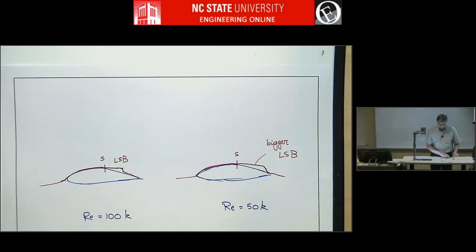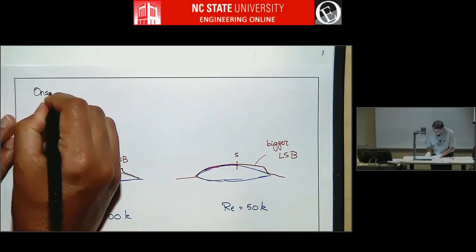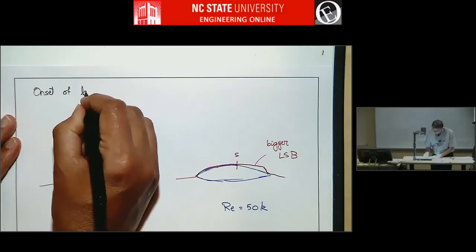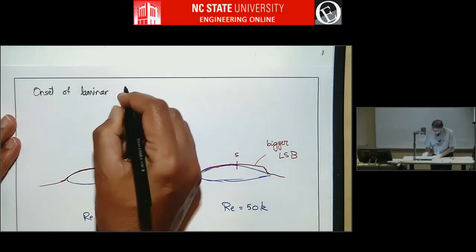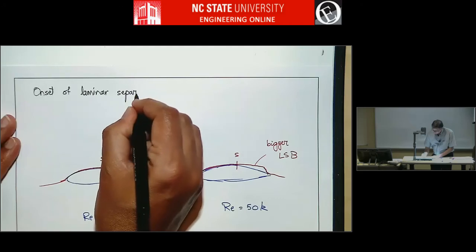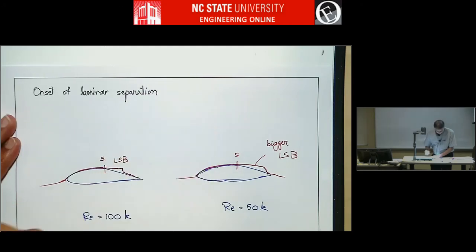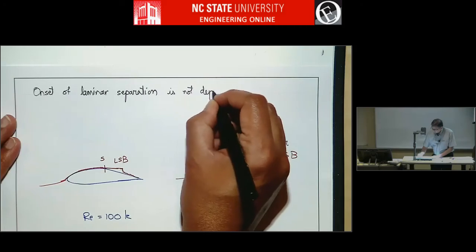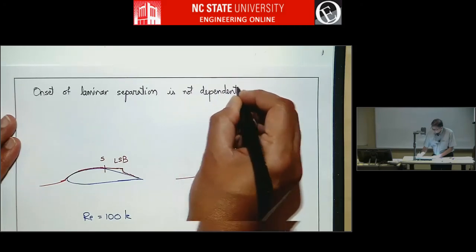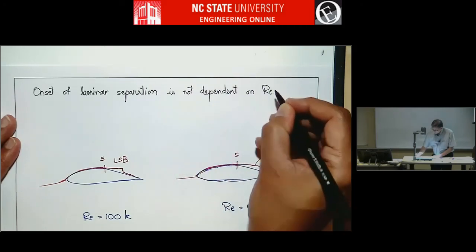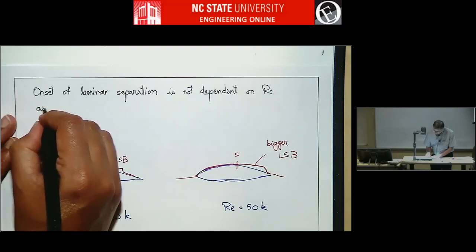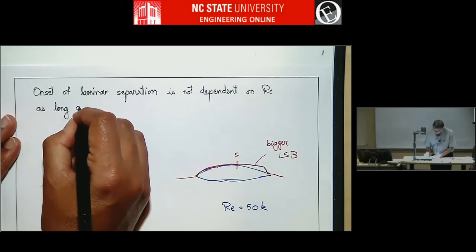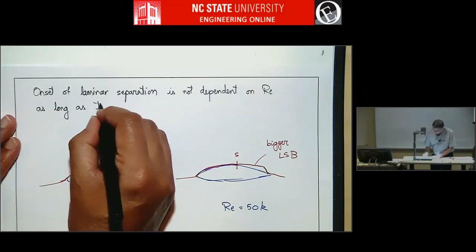But anyway, the point is, the onset of laminar separation is not dependent on Reynolds number, but only as long as transition does not happen upstream.